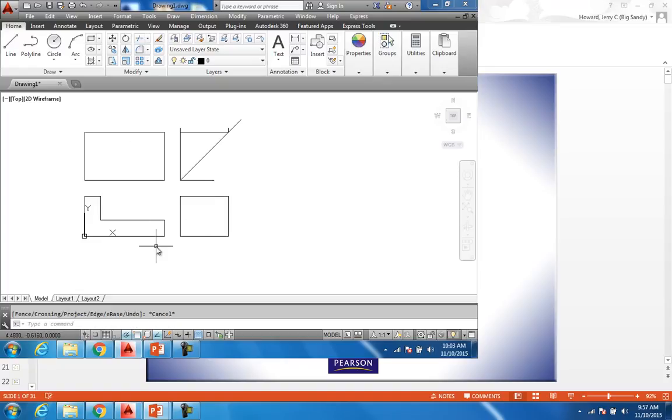Pretty easily set up. Now, again, you have 3 dimensions. Of course, on this one you have your width and your height on the front view. The top view, you transfer your width up, so you'll have width, and then you have your depth of it. Right side view, you're going to transfer over your height, and then your depth comes off the top view, or vice versa. So now I'm going to go ahead and put the rest of the stuff in.